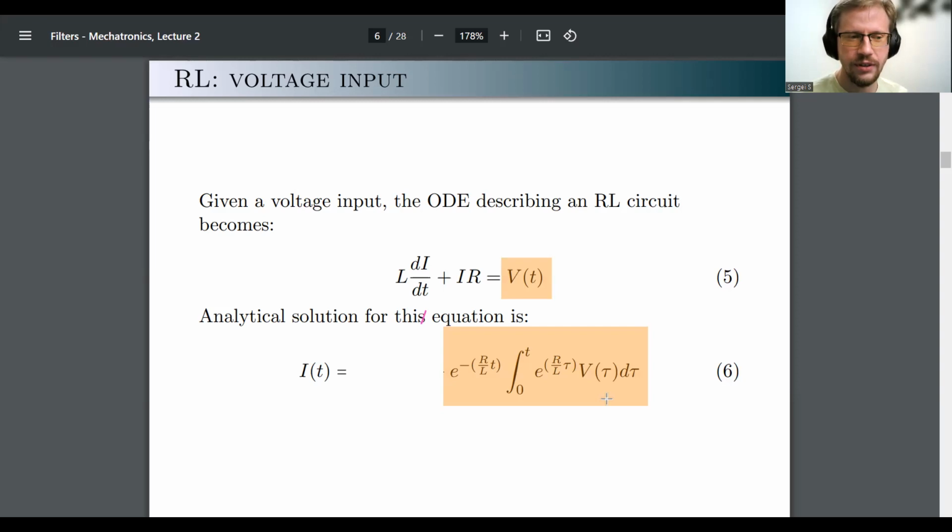If the input was constant, we could talk about steady state response, right? But since the input is harmonic, the particular solution is also going to be harmonic. For me, it somehow makes sense to call it steady state in the sense that it is repeating itself. The transience, where we have something constantly changing, is over. We just have a repeating pattern, which is perfectly described by phase and amplitude. But I understand that steady state also sounds like a constant. Constant and steady state sound like synonymous words, so maybe it's an unfortunate choice of words. I'm not sure. But hopefully I explained the essence of the issue, right?